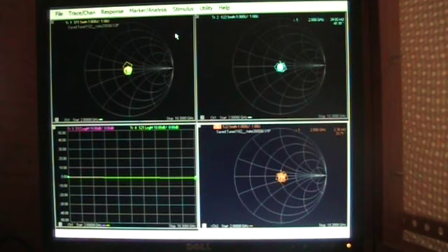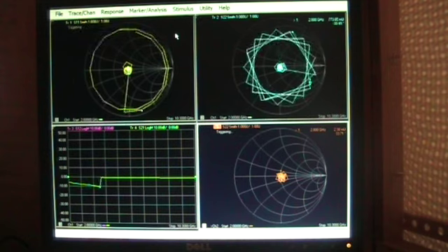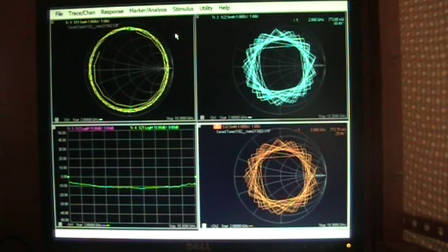We're going to go ahead and move the tuner into a position where there's a very high reflection coefficient presented, and then we'll take a quick measurement. So here you see that there is indeed a higher reflection coefficient that's presented to the device. So you can see it up here, and then this is the actual gamma source that you'll see from 2 to 10.3 gigahertz in 100 megahertz steps. Most of them are all floating around in the 0.77 range for this particular case.